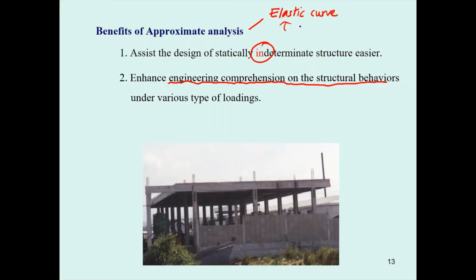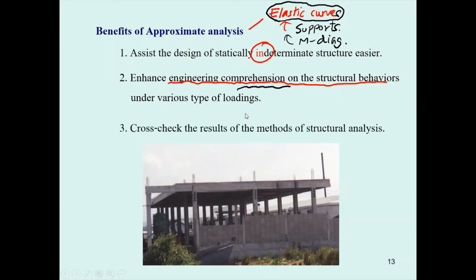And if you are going to consider the elastic curve of the structure, you got to understand how the structure is supported, and you also got to draw a correct moment diagram in order to estimate or draft a good, correct elastic curve. Okay, that requires you to gain more comprehension of the structural behavior.